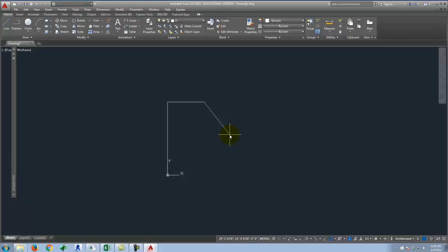Now, sometimes it's difficult to calculate in your head where these points would be. Okay, so I'm using what are called absolute coordinates right now. If you just take x and y, I'm typing in values of where they'd be on the graph. Sometimes you just know where the point should be relative to the last point you clicked. And so I'll use relative coordinates instead. What relative coordinates do is they replace the origin with the last point that you clicked.